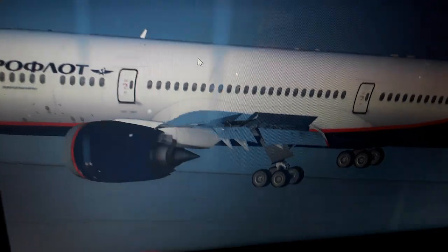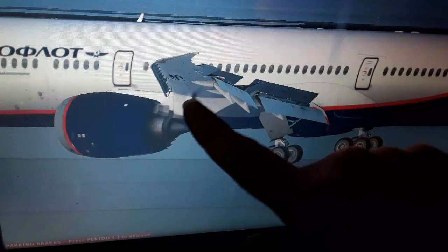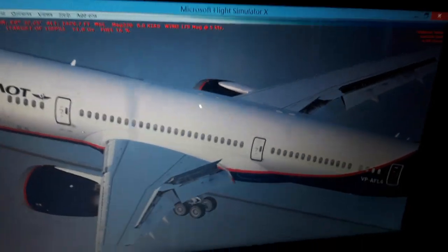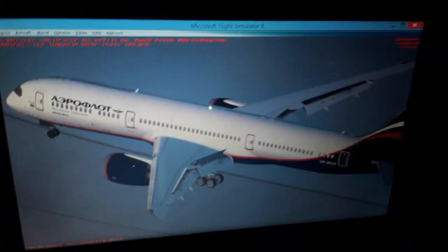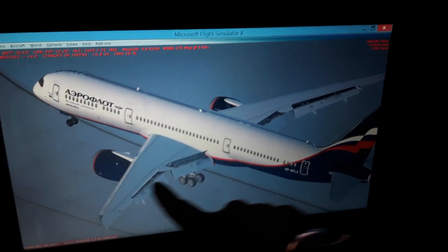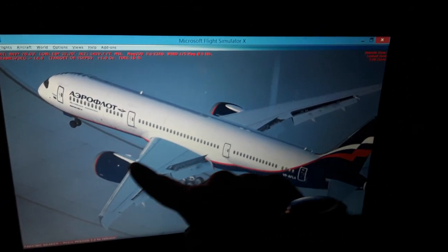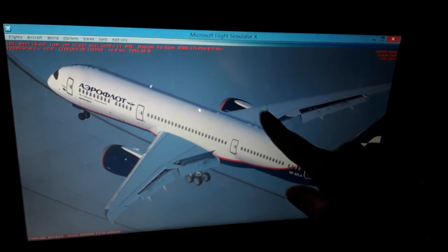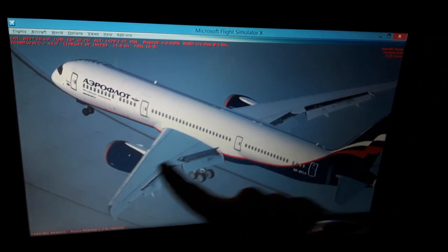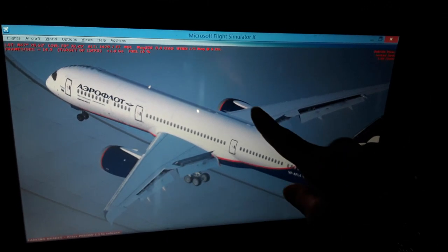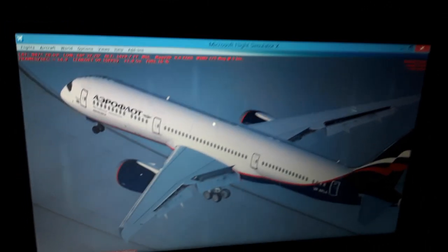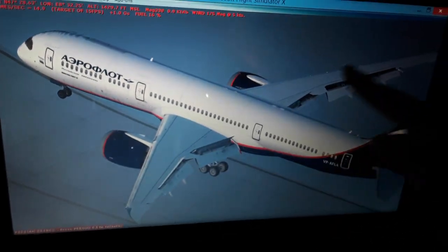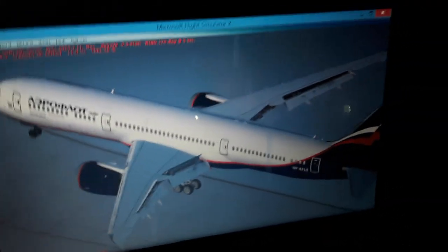We have the fuel over here. The fuel is coming down to the engines from the left and the right wing fuel tank. So you can see we have two engines for symmetric thrust. Also left and right wing fuel tank, the fuel booster pumps over here, and the fuel valves, low and high pressure fuel valves. So we have 30% and 30% in the left and the right wing, and 10% in the center wing fuel.